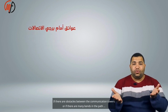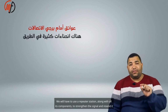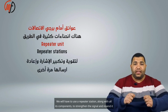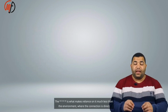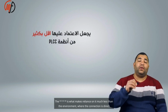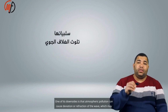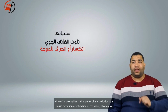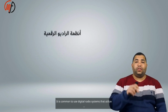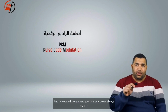If there are obstacles between the communication towers, or if there are many bends in the path, we will have to use a repeater station along with all its components to strengthen the signal and resend it again. Its advantage is that reliance on the environment is much less, where the connection is direct between one end of the line and the other. One of its downsides is that atmospheric pollution can cause deviation or refraction of the wave, which may reduce the efficiency of the transmitted wave. It is common to use digital radio systems that utilize pulse code modulation, and here we will pose a new